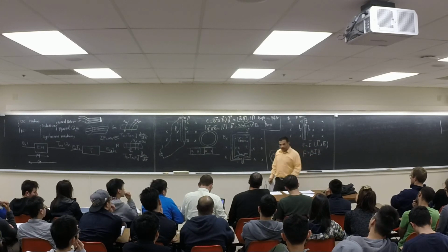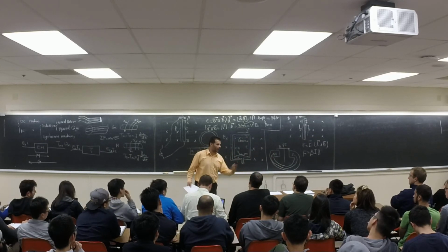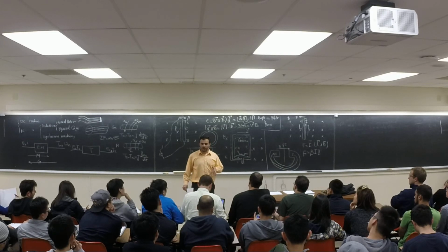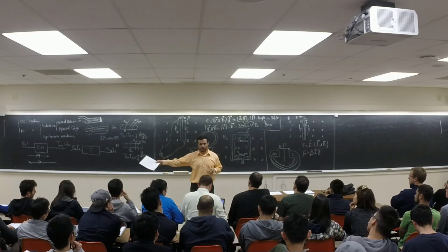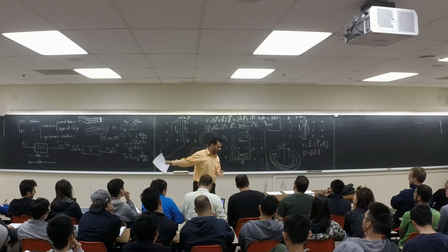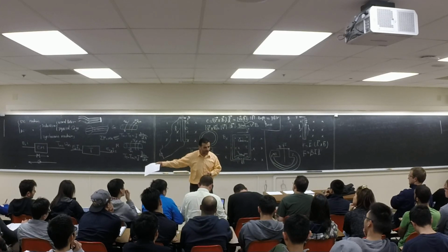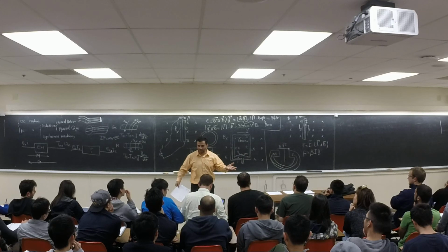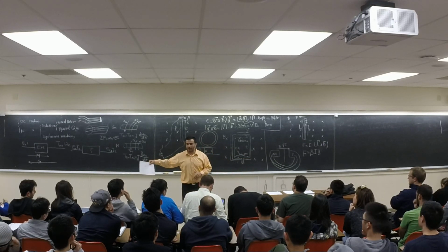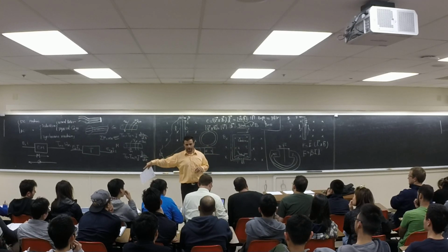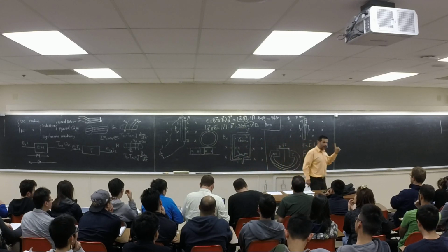So if you want a very high torque machine, one way is to put a huge current into the machine. But there is a limitation by your source first. Let's say you have this outlet here. It can give us a maximum of 16 amps. Now I want a torque equivalent to 10 times this current. What should I do? I'm going to put in 5 turns. 5 turns end up as 10 conductors, and 10 conductors times this current looks like one conductor with 10 times this current. So to increase the force or torque, either you can increase your current or you